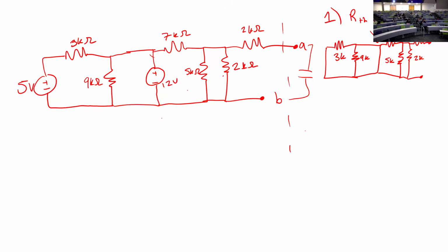It doesn't spread through components. So for instance, if I plopped it right here, I would draw this loop. It goes there and then there. So all of that is one node. All of that is one wire. Because a wire only stops when there's a component on it, when I'm going through a resistor. The actual line doesn't mean anything. It just means how I'm connecting. Okay. So all of this, say, would be like node capital B. Or let me change letters. We'll call this maybe C.